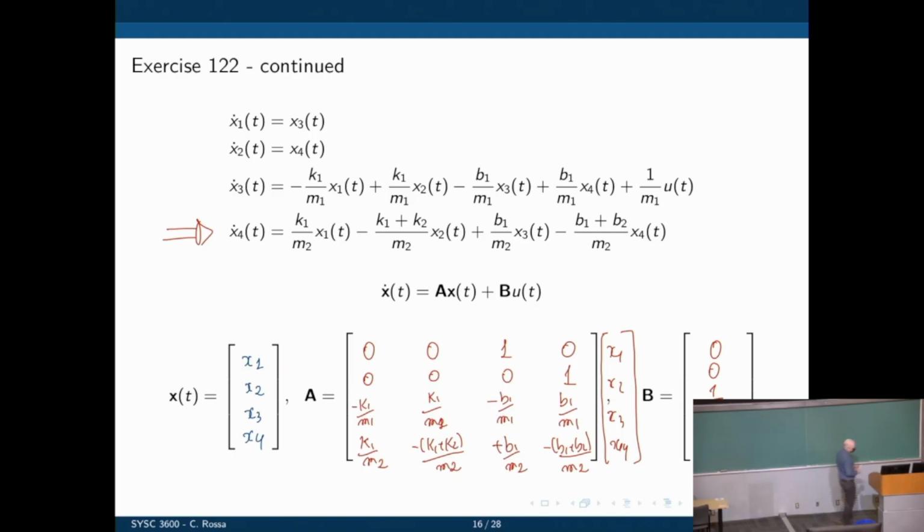So those that are home, you can see B. I'm going to write B here because my image is in front of it. It is 1 over m1, 0. Now notice that if we go to the equation in the center there, x dot equals Ax plus Bu, and you multiply everything out, we go back to the 4 equations we had.